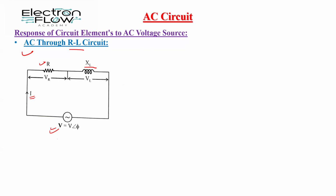When the current I passes through this resistor, it causes a voltage drop of IR, which is in phase with the current. So we can write the voltage drop across the resistance: VR is equal to I times R. Since it is a series circuit, the current phasor is taken as a reference. If I draw the phasor diagram, it will look like this.